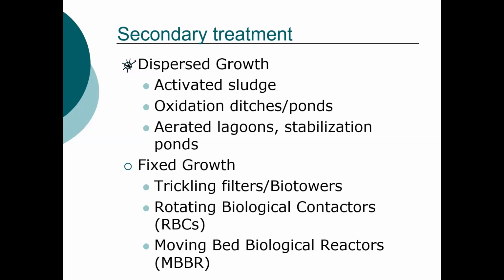The second larger group is fixed growth. Again, think of the river, think of the rocks in the river and the moss growing on the rocks. The water flows past the rocks, past the moss, but that water is still providing nutrients to the organisms that are attached to that rock. Same type of thing.